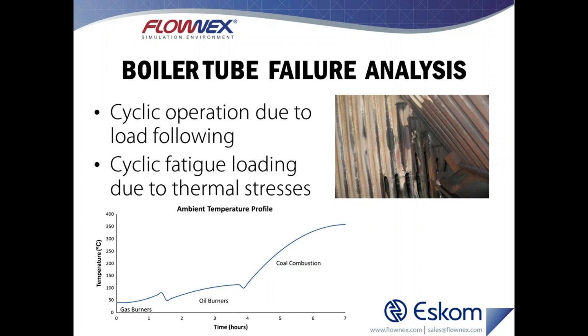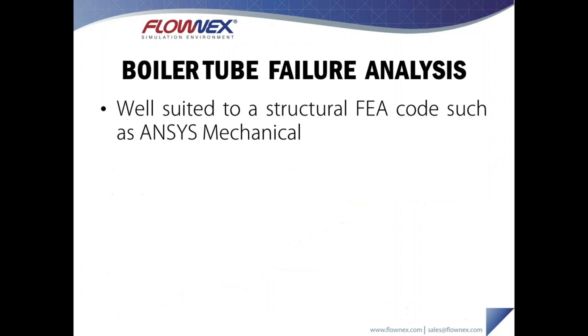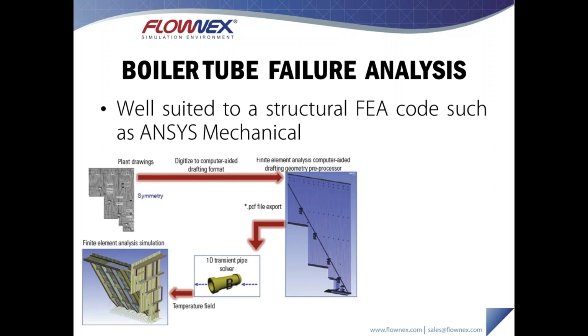And this creates those cyclic or those large thermal stresses inside of the system. So to properly understand this, the engineers at Eskom used a structural code, in this case ANSYS mechanical, and Flownex to simulate those particular flows inside of the boiler and calculate the stresses that result.